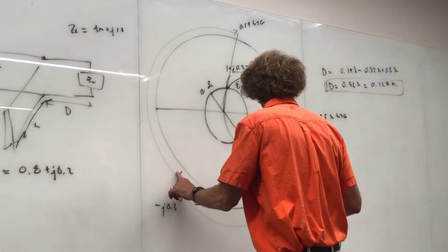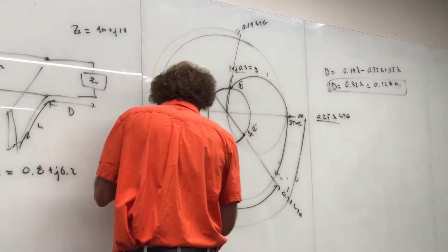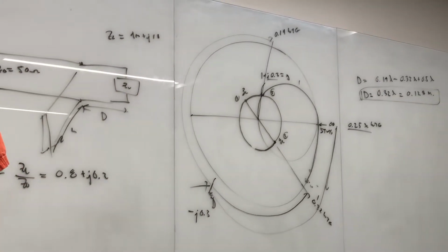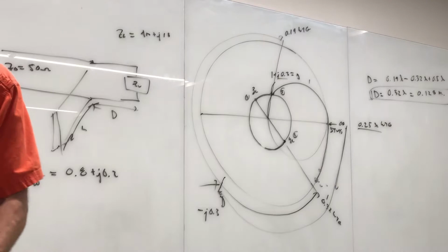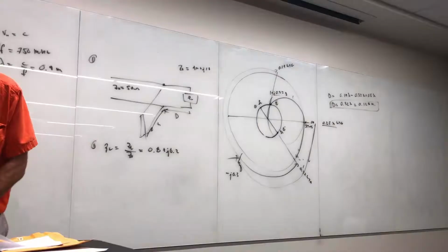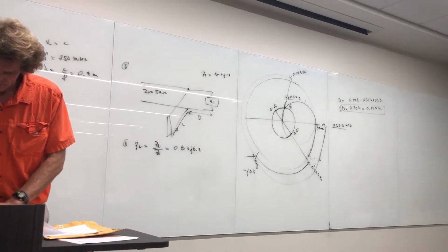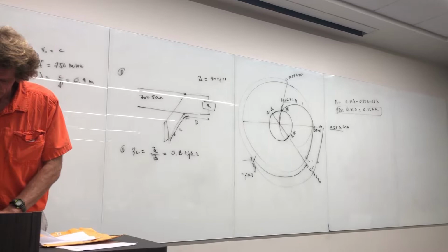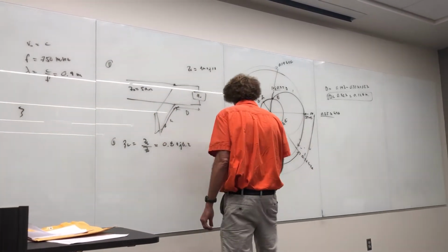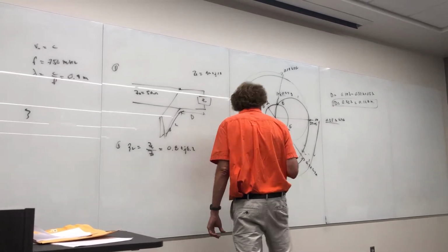Now, I need the distance, so it starts at 0.25 lambda, and this point, I don't remember it off the top of my head. 0.45, is that what you have? This is 0.45 wavelengths toward generator.